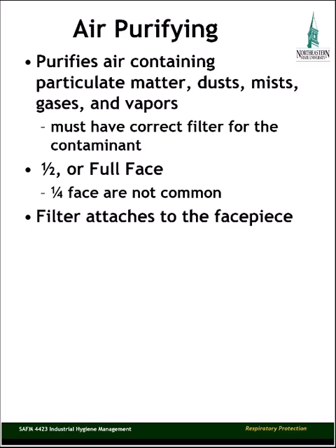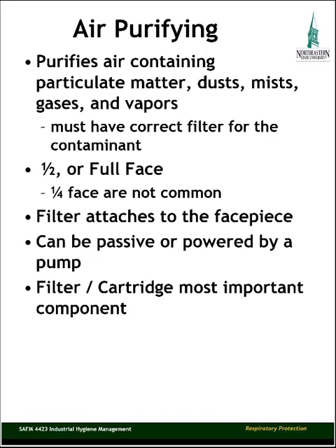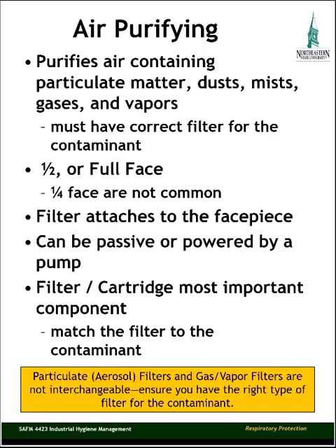With these types of respirators, the filter attaches to the face piece. Most of them are going to be passive, but some of them may be powered by a pump. And the filter cartridge that's selected is most important. The filter must match the contaminant. An important point about matching a filter to the contaminant. Particulate filters and gas or vapor filters are not interchangeable. Ensure that you have the right type of filter for the contaminant.